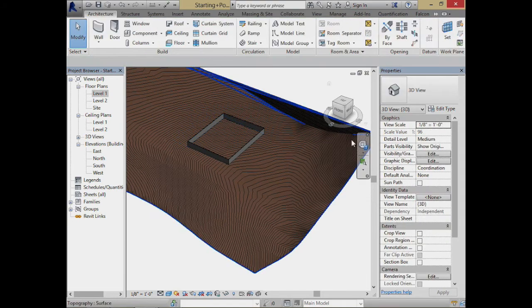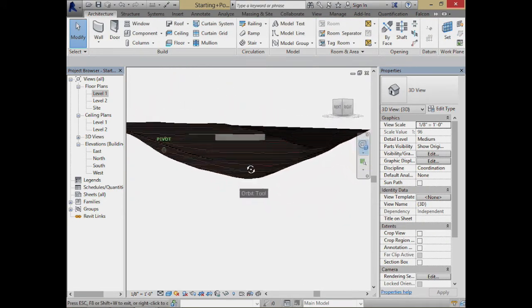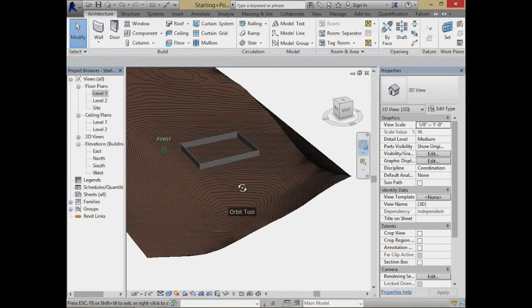if I rotate it around a little bit, you might see that it's kind of up or down relative to the site. And if that is the case and you want to nestle it down into the site or something like that, that's actually pretty easy to do. It's going to sound weird, but it's actually easier to move the earth than it is to move your building, because it's just a matter of what the base point of your building is.